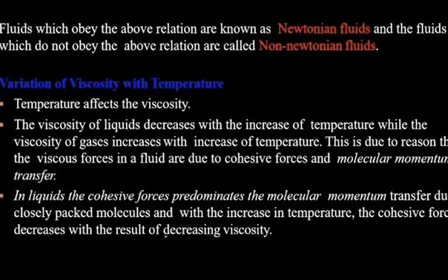This is due to the reason that the viscous forces in the fluid are due to cohesive forces and molecular momentum transfer. In liquids, the cohesive force predominates over the molecular momentum transfer due to closely packed molecules. With the increase in temperature, the cohesive force decreases, with the result of decreasing viscosity. When there is no cohesive force, there is no question of shear strain, and so viscosity will not be there.